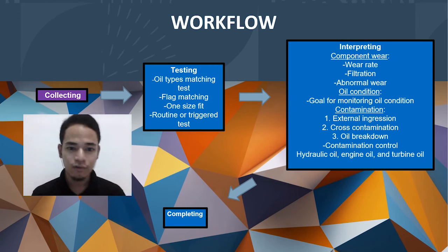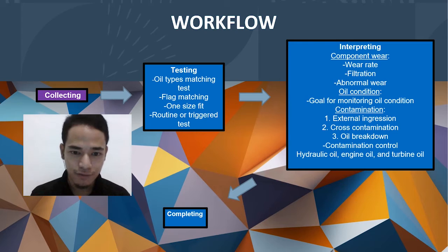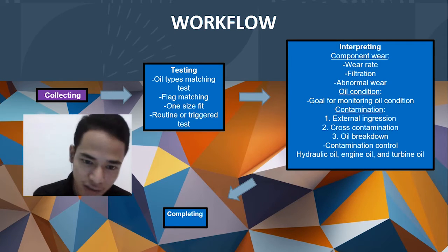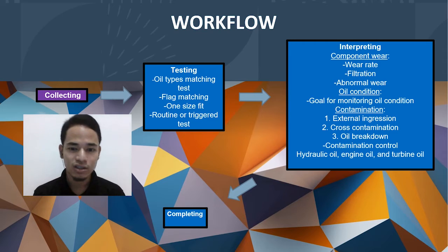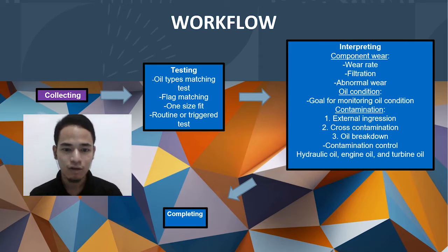So the goal for monitoring oil condition is, first, confirm the correct oil is being used, and second, identify when oil should be changed. Third is maintain oil condition for as long as possible or as long as needed.